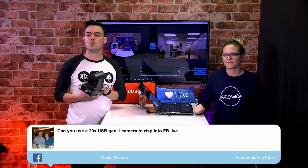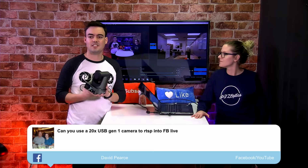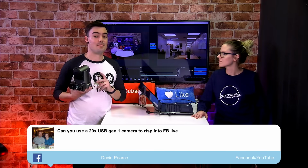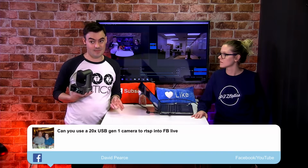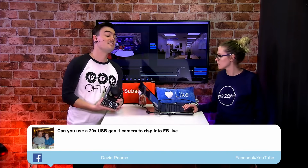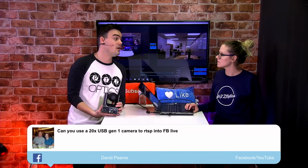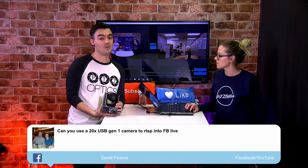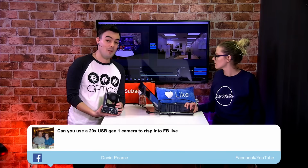Can you use the 20x USB Gen 1 to RTSP into Facebook Live? I'm going to go ahead and say probably no, for two reasons. One, you'd have to use RTMP, not RTSP. And the Generation 2 cameras just had that added in. So I don't believe the Gen 1 cameras can directly RTMP stream to Facebook. It's possible, but I don't believe so.